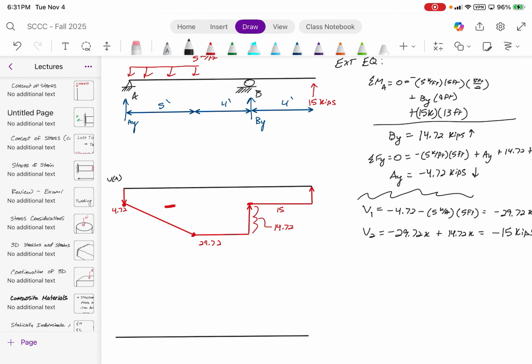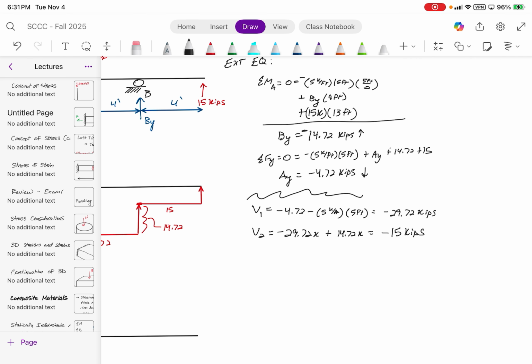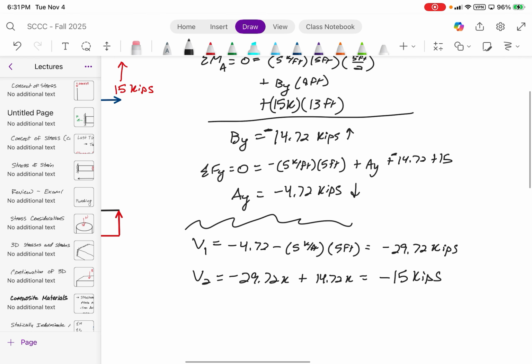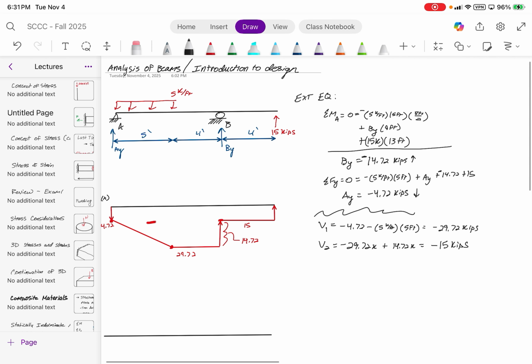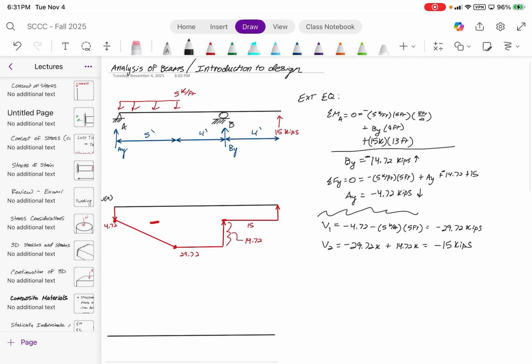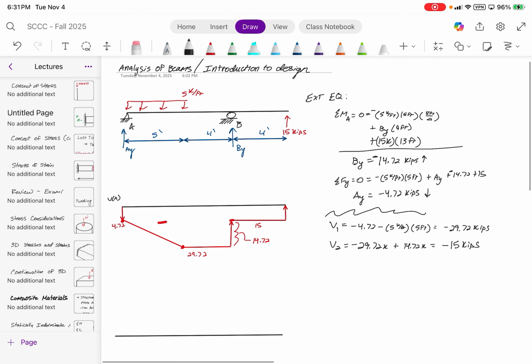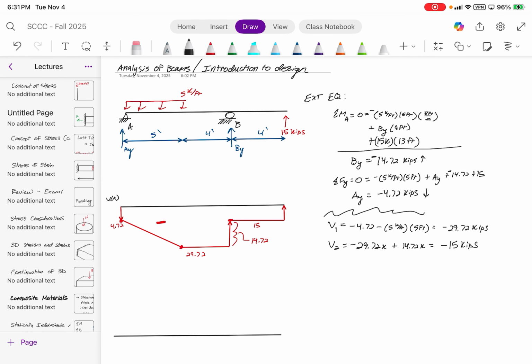Which means that this is going to be negative. That is negative. Yeah, because I was just thinking, you can kind of see the shear force diagram closes out to 0, but at that point, it's going to mess up your bending moment diagram, because it's going to tell you that it's not going to close out to 0, because if you're just summing negative moment the entire time, it's not going to close out to 0 at the end. So that's a good point.